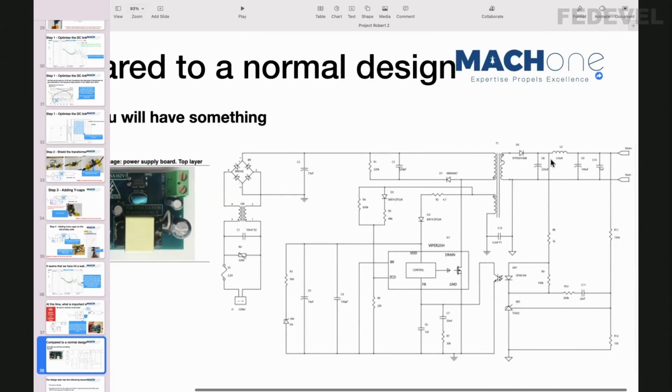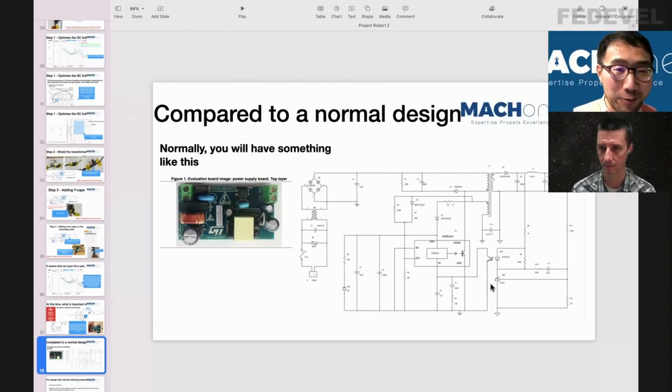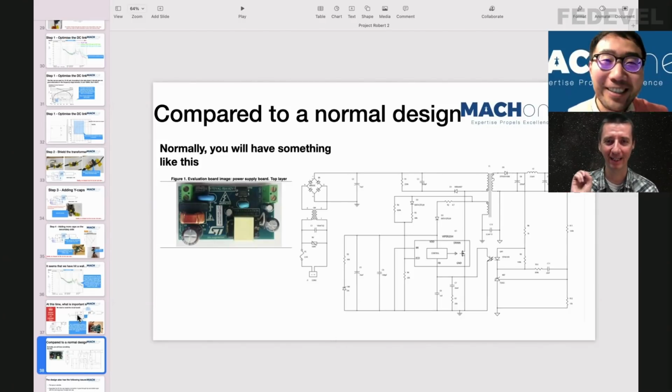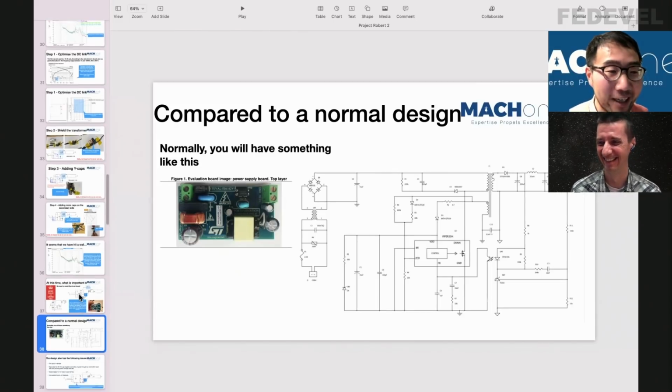And then if you look at their schematics, you will see, wow, look. On the low voltage side, they have an LC filter. On the high voltage side, they have a capacitor and common mode choke. This C1 is the X cap. I was using very similar techniques, and you can see their chip is much more complicated than the one we just saw. So you know that for these low cost solutions, they took everything else out. That's the challenge. They remove a component and say, still works. Remove a component, yes, still works. Always works. I'm pretty sure that's how they did it.